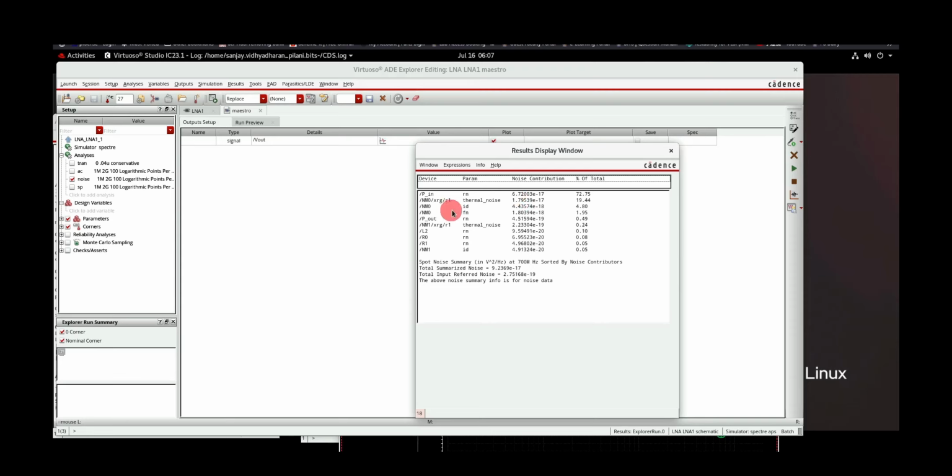And then the input transistor: you can refer to my lecture on noise, this transistor has several noise components, ID noise, flicker noise, thermal noise. Which component of that MOSFET is contributing what kind of noise, all the details can be seen. Depending on this analysis, if you find that you need to adjust a few things to reduce the noise, accordingly we can do an analysis and then try to minimize the noise. We can't blindly change things; once you go through the lecture on noise, you will come to know how to reduce these noises.